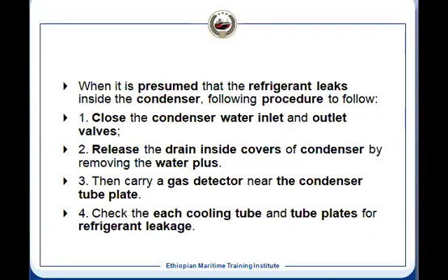Okay, Abraham has a question: if we use the halide lamp, there are chances of fire. It is a fire hazard. Number one, we cannot use it unless it is compatible with HFC. But when you are using the torch, you as a person have to take safety measures so that it does not catch fire. You can keep it a bit away. It is not needed that you touch the flame to the surface. Once it is leaking, the area will be surrounded by the refrigerant.